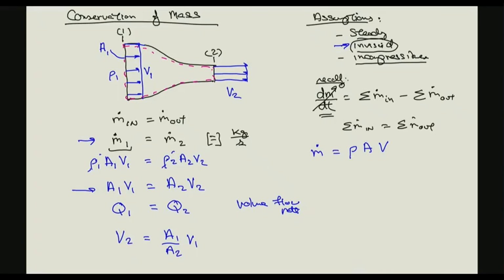So I think that's all I want to do for the conservation of mass. Okay, typical units for SI, meter cubed per second, or English units would be GPM. What's GPM? Gallons per minute. Okay, so if you've ever measured GPM, you take a bucket, a gallon bucket, you got your hose, you got your watch. In 1 minute, how many gallons are coming out of that hose? And there you can get your GPM for your hose.